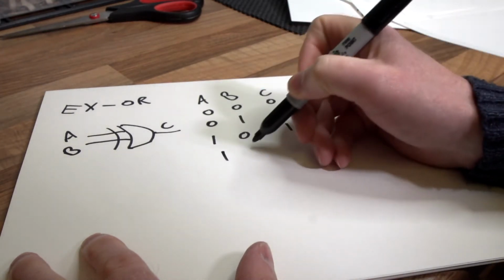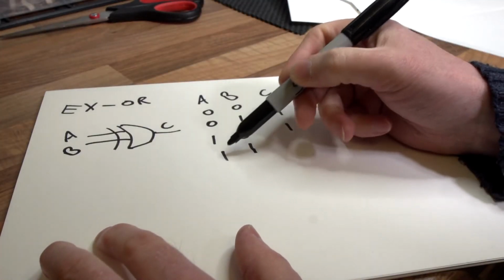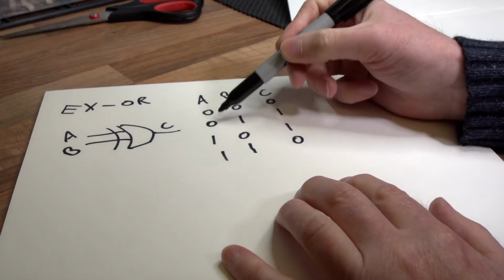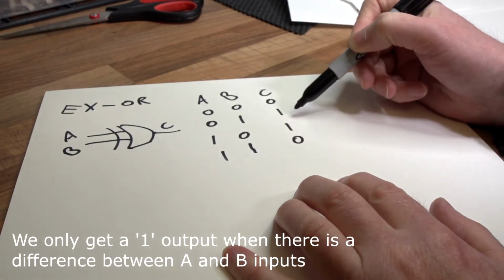And what about 1, 1? Both inputs high, both switches on. Well, they're the same. 1 equals 1. So the output is 0. So you can see that only when there's a difference of the inputs, these two conditions here, we'll get a 1, a true output, if you like.